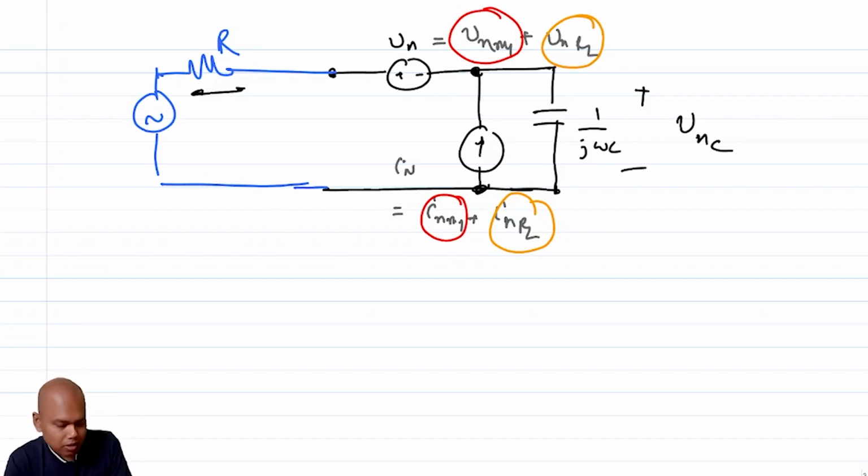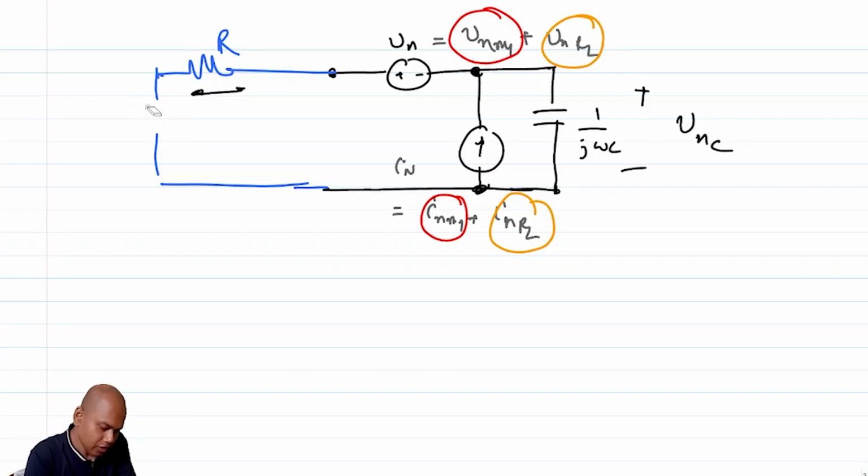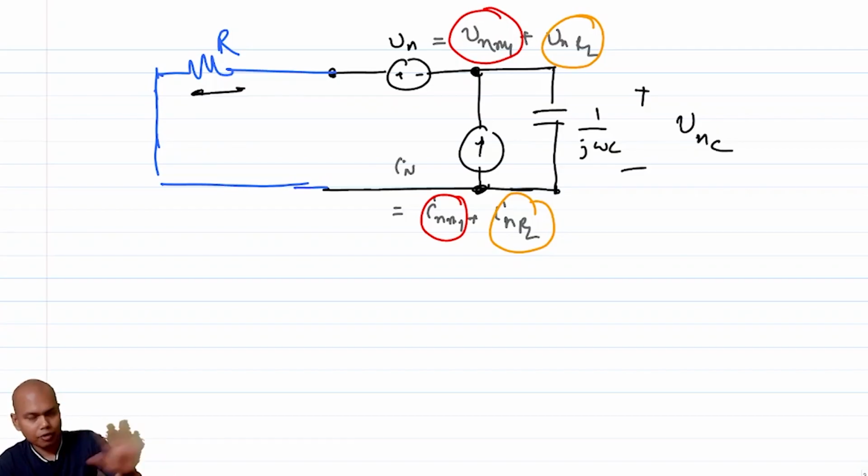I am trying to figure out the noise due to my input referred current and voltage sources across the capacitor. To do that, I will desensitize everything other than the noise sources of interest. While finding noise, I do not need any input signal source, so I can get rid of that. I'm not doing the calculation for the noise from the R, so the equivalent noise source for the R is not used right now. We are going to use it later.